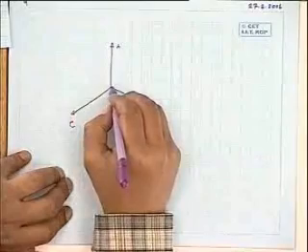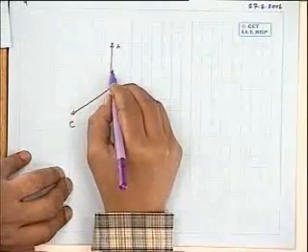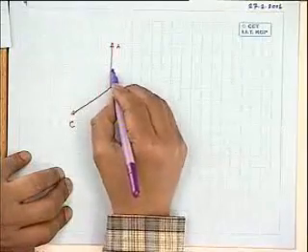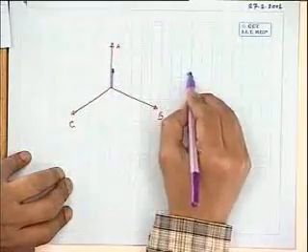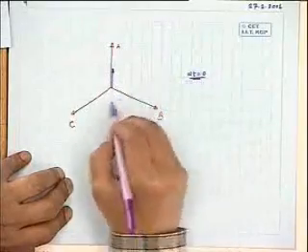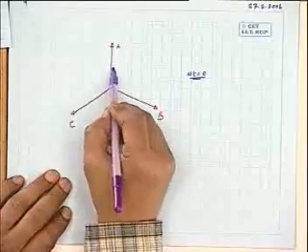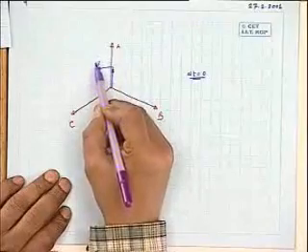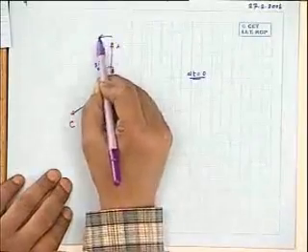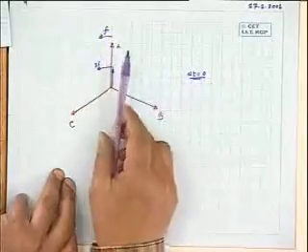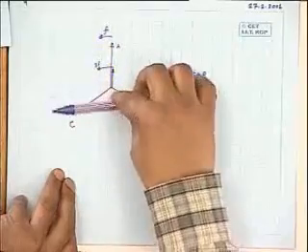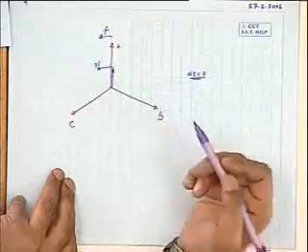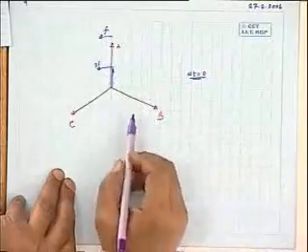Now, let us assume an instant when the third harmonic voltage is zero, and all the three voltages will be in this fashion. Let us call this omega t equal to 0. I am counting time from when this phasor, which moves with a frequency of 3f, or relatively at a frequency of twice f with respect to this, and this I will show at f. So what will happen? With time, this will sweep past all the three phases. At this instant, suppose they coincide with this A phase.